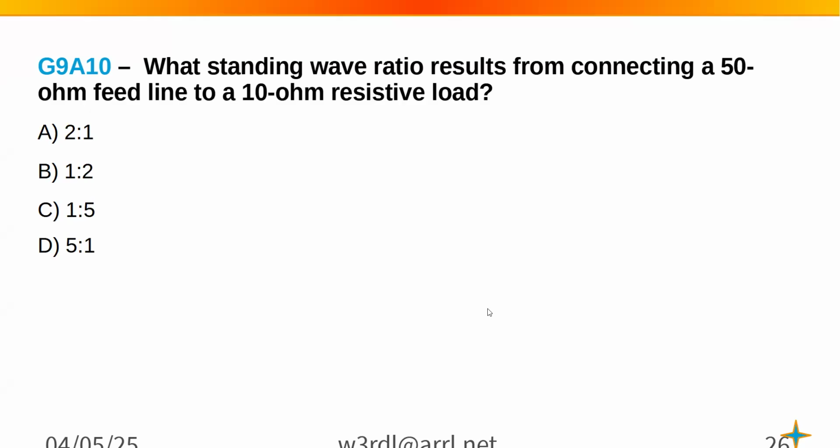What standing wave ratio results from connecting a 50 ohm feed line to a 10 ohm resistive load? It's a tricky one. Yeah, they tried to fool you with 1-to-5, because the ratio is 1-to-5, but you always go with the high number.